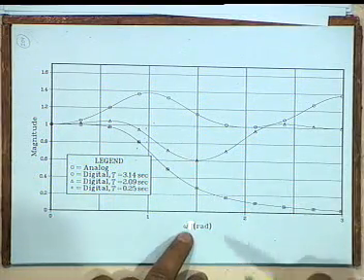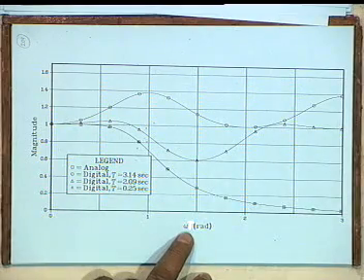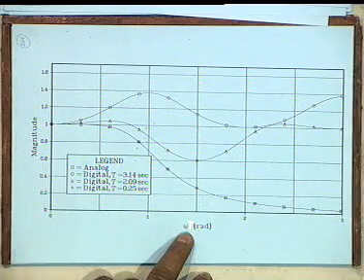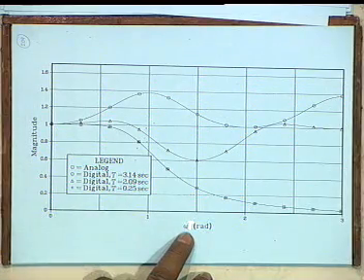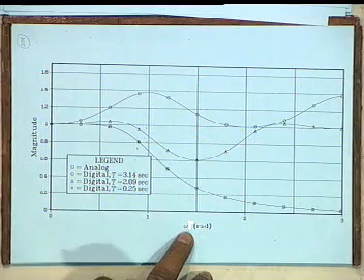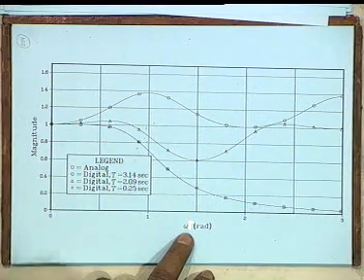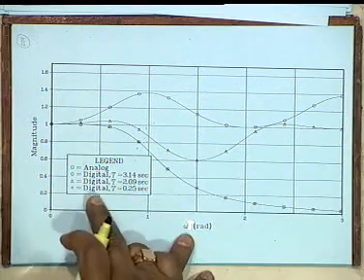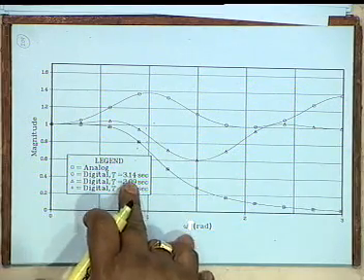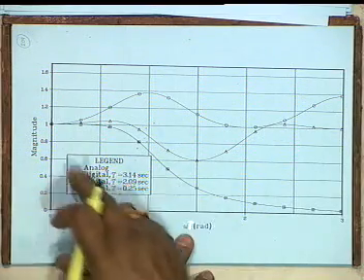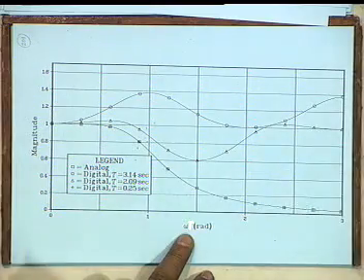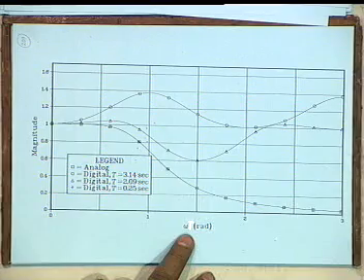Okay, what I have plotted here is versus small omega. Small omega is capital omega multiplied by capital T. Now obviously the transfer function depends on capital T, right? If you sample at a very low frequency, well, you are asking for trouble. You have to choose a good high frequency sampling. You see, if capital T, the sampling interval, is as large as pi seconds, 3.14, this is what you get. In your wildest imagination, this is not a low pass filter, isn't it? It's a band pass filter.